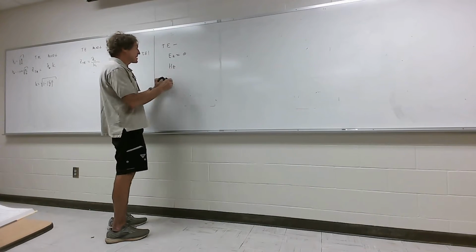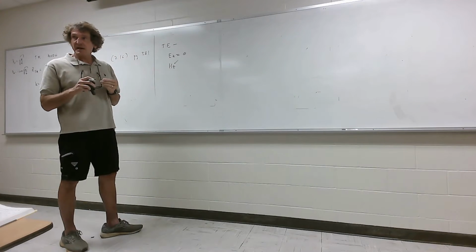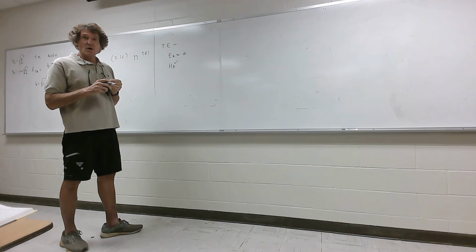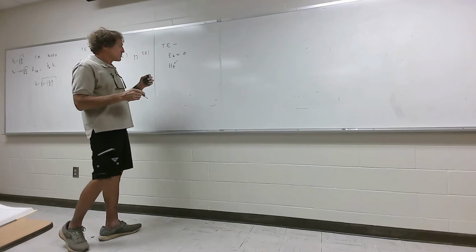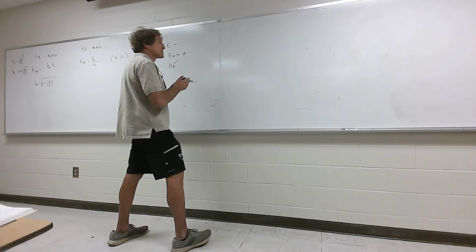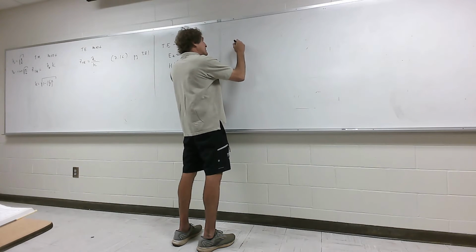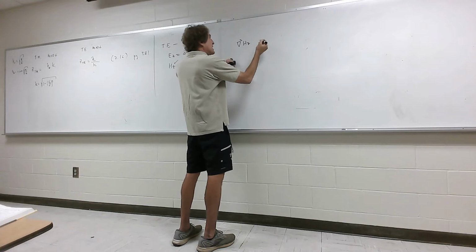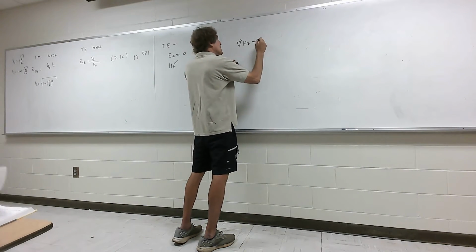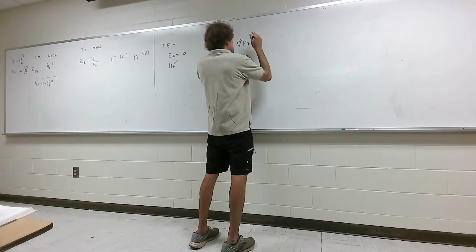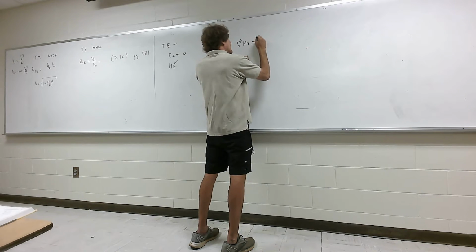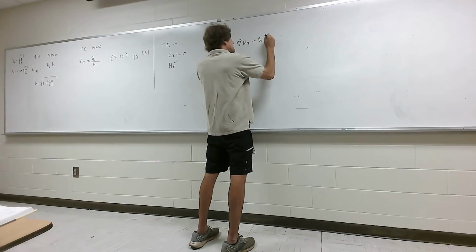So for this one, we will have an Hz, all right? Because now we're talking about transverse electric, where the electric field has no component in the direction of propagation. Before it was TM, right? We did have an electric field. Now, when you go through the equations for this, instead of having a del squared with Ez, you're going to have a del squared with Hz, plus beta unguided squared times Hz equals 0.